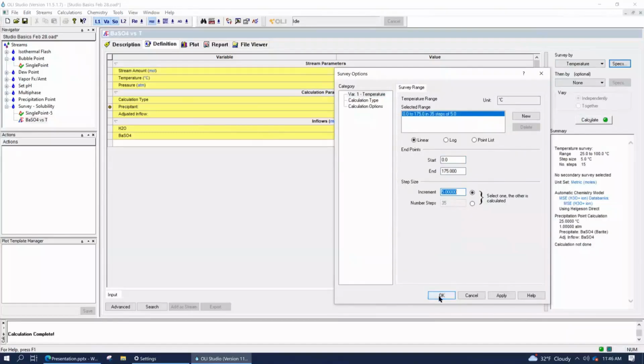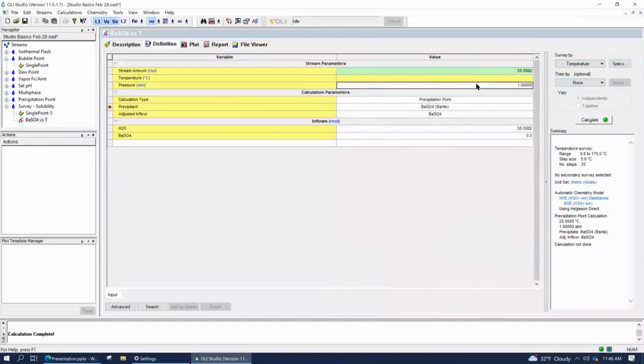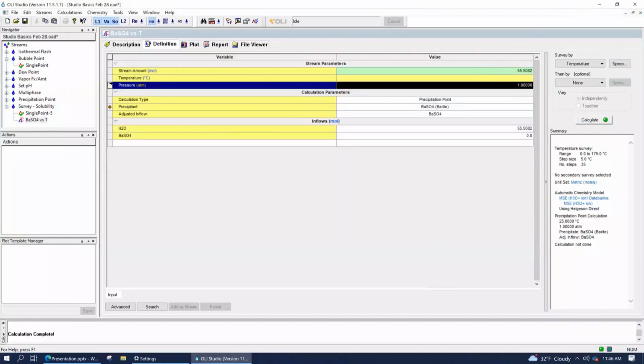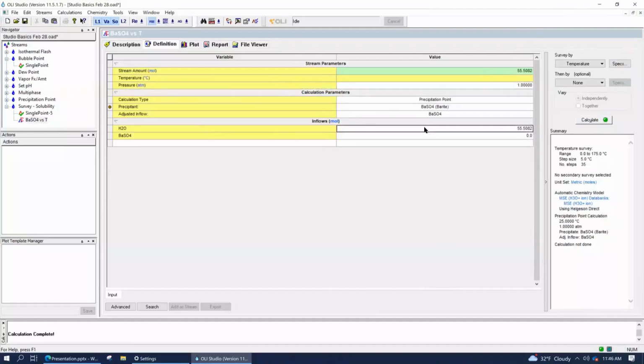Now, one of the things I'm debating internally is, should I make the calculation fail or should I tell you upfront what to do? So let me just do this, since we're running out of time. We haven't talked about this pressure yet. That pressure cell there is essentially the confining pressure on our material. Right now, I've got 1 kilogram of water, about a liter of water at ambient conditions. And I've got essentially a plunger sitting on top of that. And it's got a spring on it. And that spring is set right now to create a confining pressure of about 1 atmosphere.